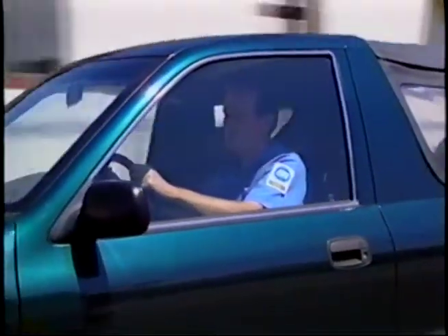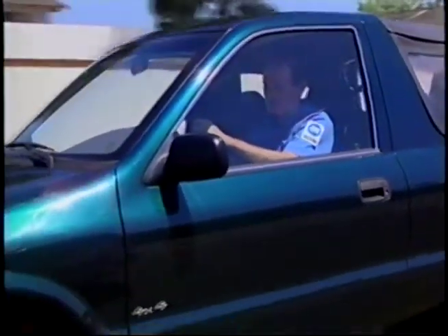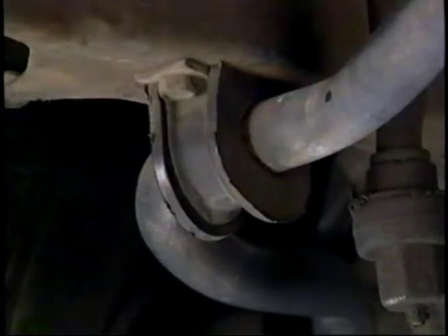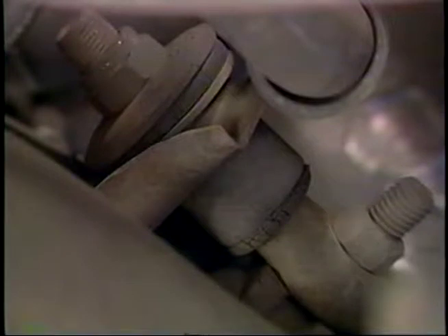Troubleshooting suspension problems relies on your ability to verify the condition to get to the root cause of the problem. When diagnosing suspension noises, always start by inspecting the bushings. Worn bushings allow the components they carry to move in their mounts, causing metal-to-metal noises. Worn bushings usually cause noise during suspension movement, and they must be replaced.